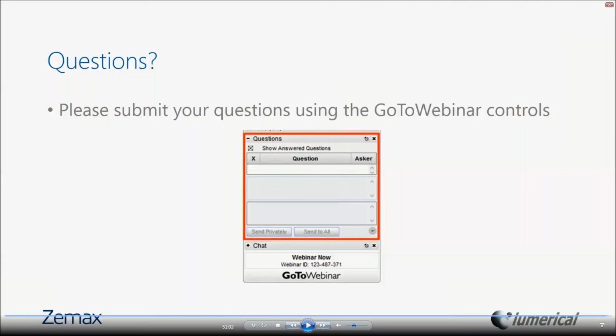And I just have another question on how, can you explain how you build the 3D lens model in Lumerical? So yeah, it was actually really easy. I just have a script that reads off my desired phase profile and then reads off the duty cycle map, and then it positions it, basically figures out what the duty cycle is. And we will be putting that example online shortly, so you can use the scripts. I'll share the scripts that I use, and you can download that. But I'm just pasting here in this chat window.